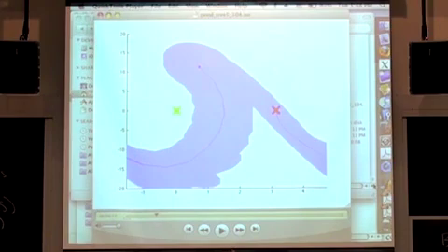Yeah? If I start the system inside any of that blue region, and I execute the trajectory, the LQR trajectory stabilizer along that trajectory, it's going to take me around and get me to my goal and stay there. Okay? So this is feedback motion planning happening. Now the cool thing is I told you about the multi-query idea. I told you about all these ideas, talking about making very dense trees that handle all these situations.